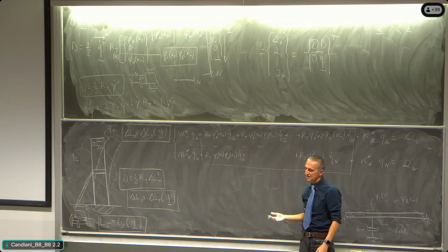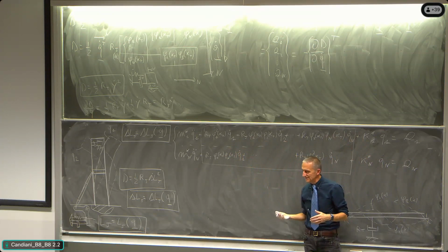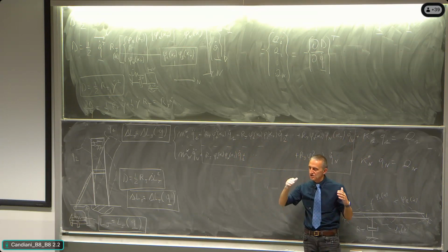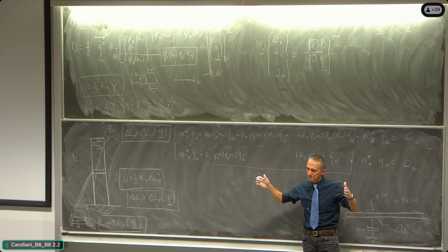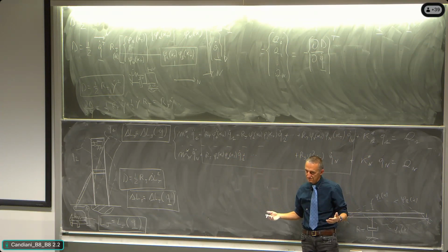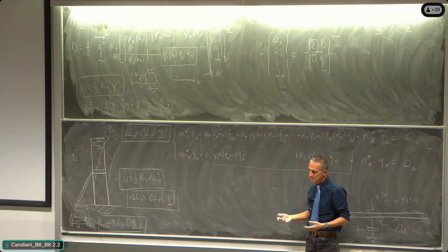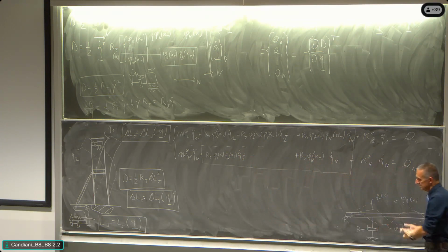And so it will not happen that I give an initial displacement along one single mode, and the system goes ahead moving and keeping that mode excited. It is mixing. It is mixing everything. So it is coupling the modes just because of one single but important damper, all right?